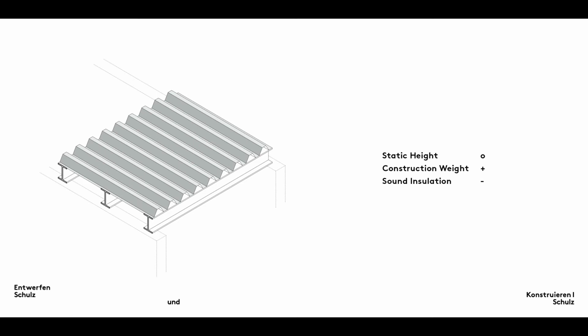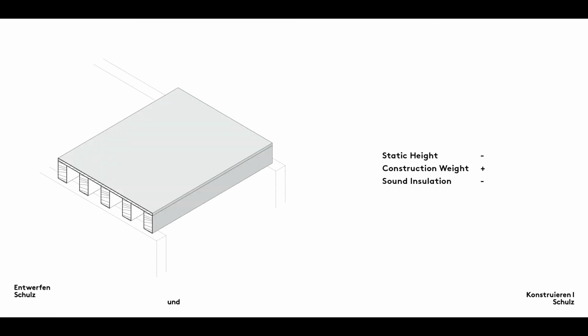Timber floors are generally constructed using wooden beams that run close together and are spanned by boards or wood composite sheeting laid between them. Although the static height is greater than for a steel construction, its dead load is similarly low. Sound insulation in wooden beam floors and ceilings presents a significant problem because of the low mass of timber.